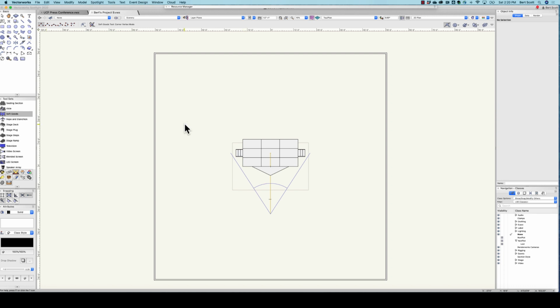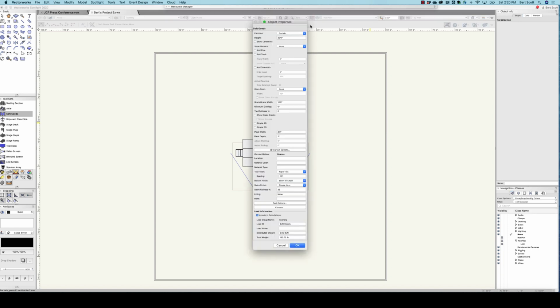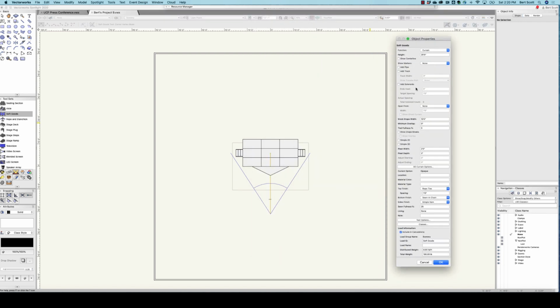So I'm going to draw a line here. I'm going to tab. We're going to do 80 feet worth of curtain, and then return, hold down Shift, and click twice. And then it will pop up and ask you some questions. Yours probably says 10 feet.